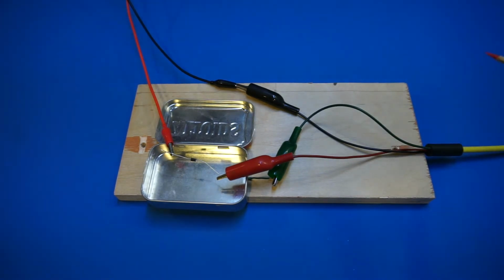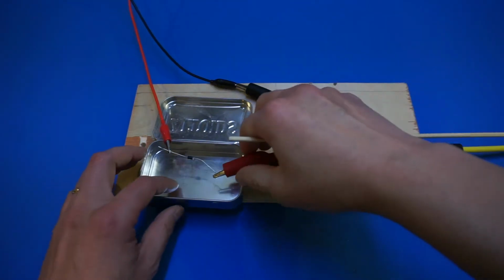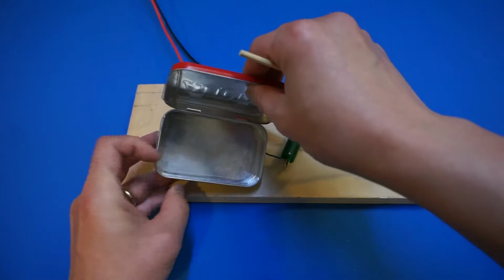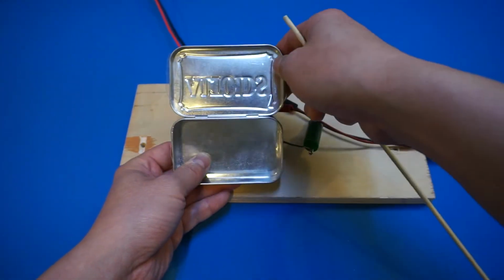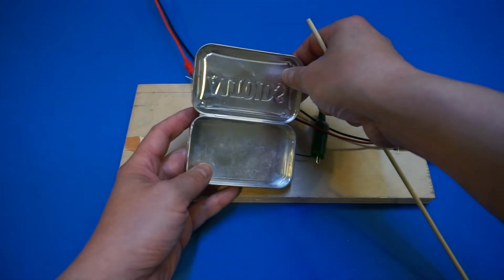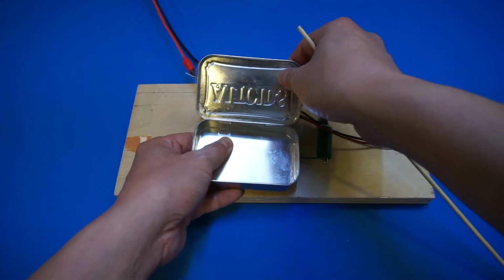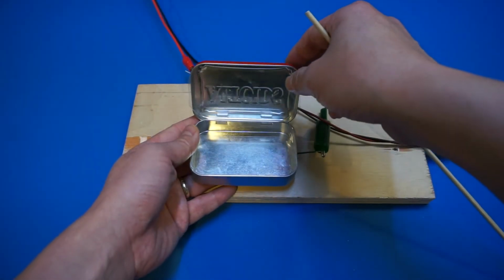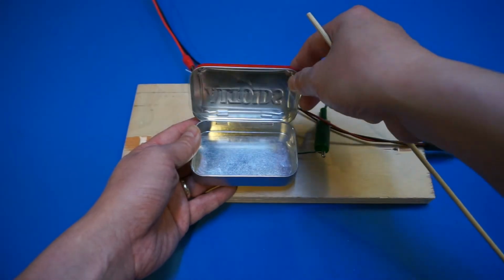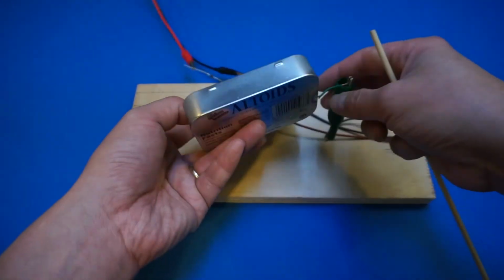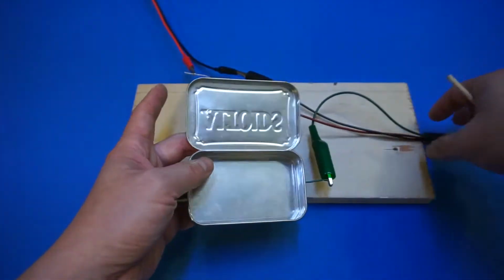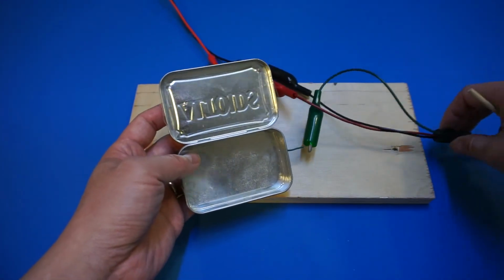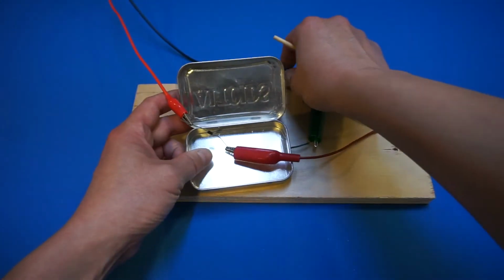And because the current is so minute, the noise is very high. So in order to reduce the noise in the measurement, I came up with this kind of a poor man's shielding device, and you can see that the inside is actually lined with tape, so that it doesn't short out the components inside. But this Faraday cage essentially is grounded through the triaxial cable, so that helps to reduce noise.